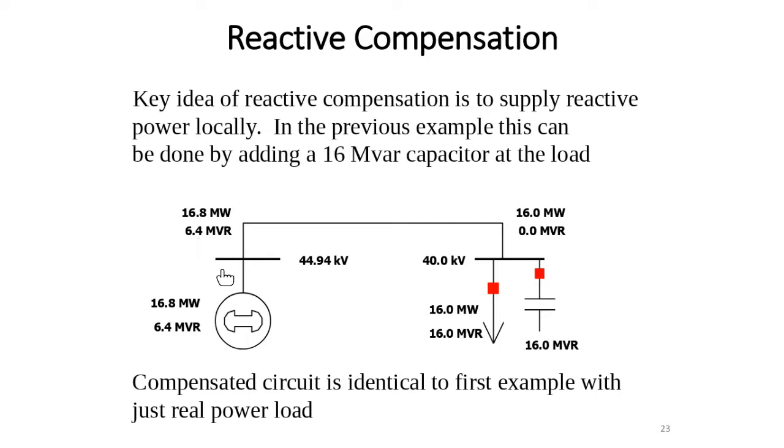Second, the voltage here is higher than this voltage. It means that this bus injects reactive power, so the reactive power goes from generation to the load.